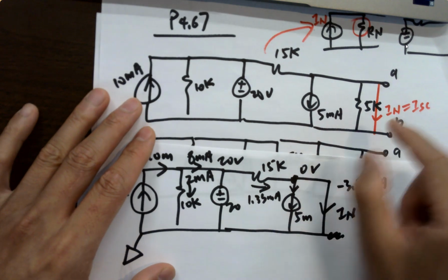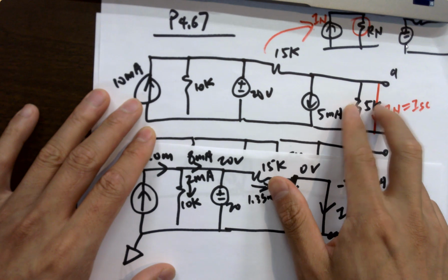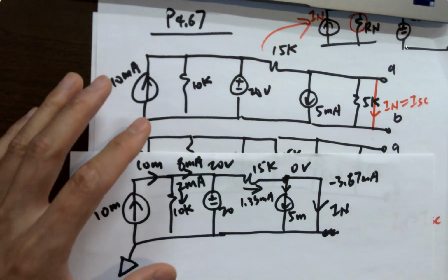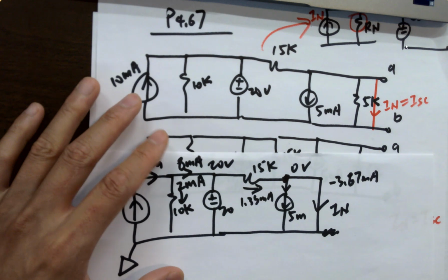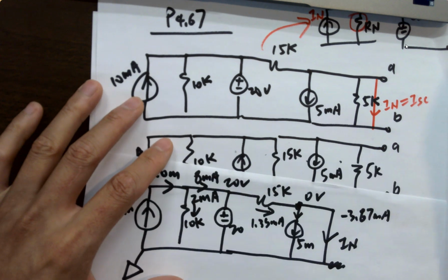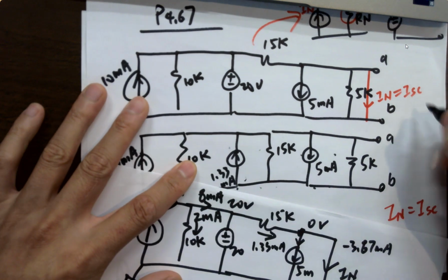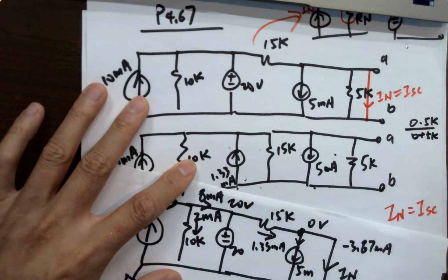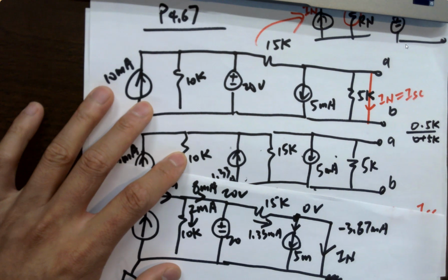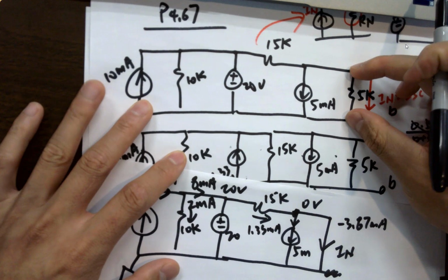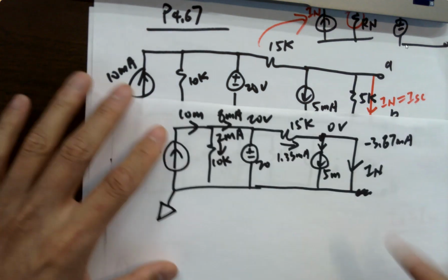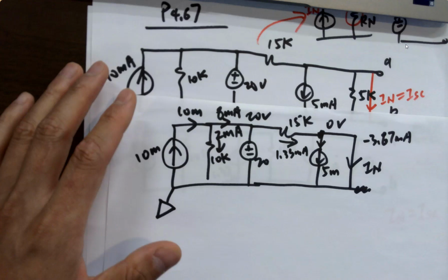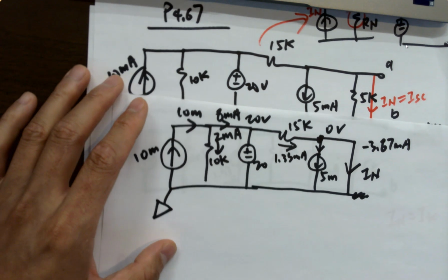Another way to think about it is, if you drew a wire here and you got a resistor, can you calculate the combined resistance? It's a parallel resistor. A wire is also a resistor with 0 ohms. So a wire and a parallel resistor, you can combine them. How do you combine them? 0 times 5K over 0 plus 5K. That's the parallel resistance. What is the resistance? 0. So a wire in parallel with a resistor, you can combine it. Did I teach you anything about a wire in parallel with the current source? Is there any way to get a combined wire? No, we don't know how to do it. We shouldn't. It's a source. Okay?